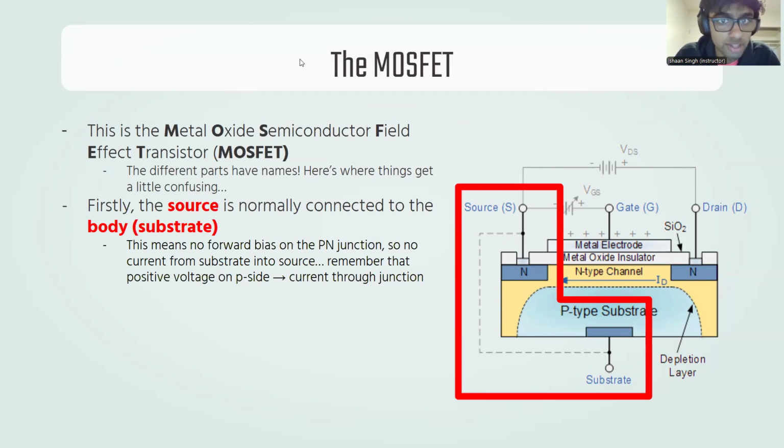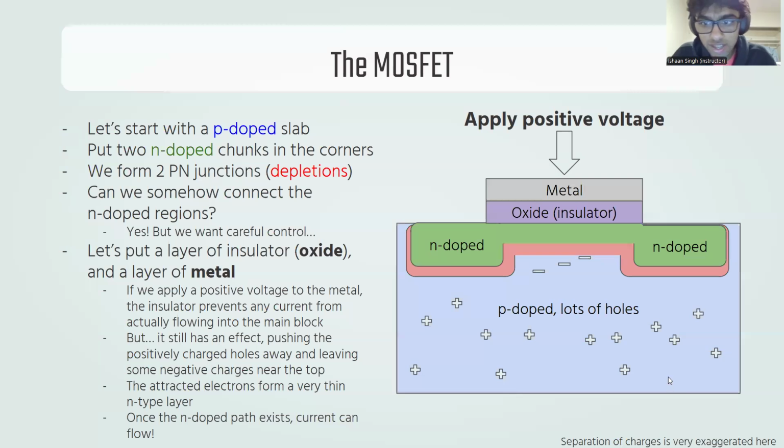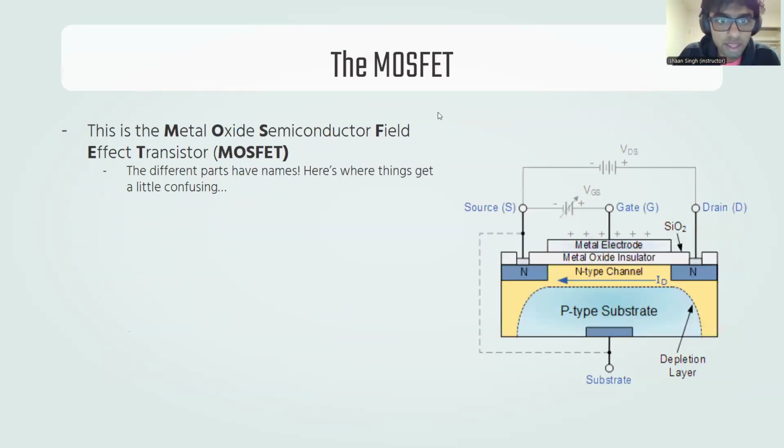Okay. What is a substrate? Good question. If you've done any chemistry, you know that we talk about substrates as where the reaction takes place. In the context of here, the substrate is this big block of p-doped material. The big guy that hosts everything is a substrate. You can think about it like just the house for all these other components. That's what a substrate is.